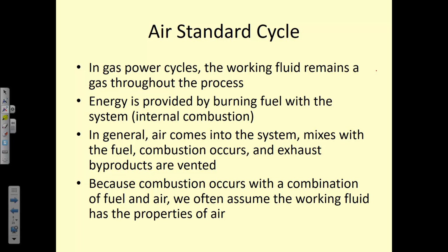So there's actually internal combustion happening, but instead of modeling this internal combustion, we just say, okay, this is our heat input to the system. We're going to look at it as a closed system with some heat input. And then we do the same thing for the exhaust, that instead of exhausting a mixture of gas and fuel, we're saying, okay, we're just going to have a heat rejection process.